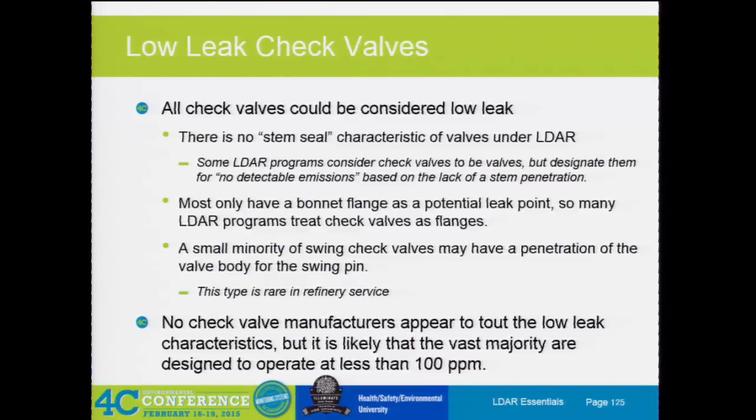All check valves could be considered low leak. There's no stem seal. As I was saying, they go in as a connector, so you won't ever really monitor them. They only have this bonnet flange, and that's the only potential leak interface.